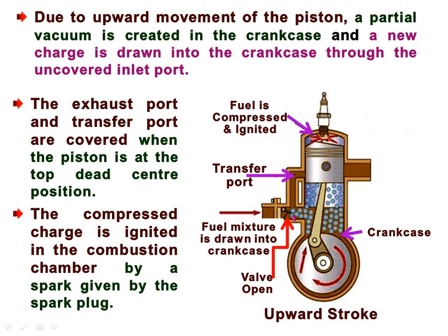So fresh air and petrol mixture is introduced inside the crankcase. This is the crankcase portion. As the piston moves upward, this port becomes uncovered, and through this port the air fuel mixture is drawn into the crankcase. So we are charging the crankcase with fresh air fuel mixture.